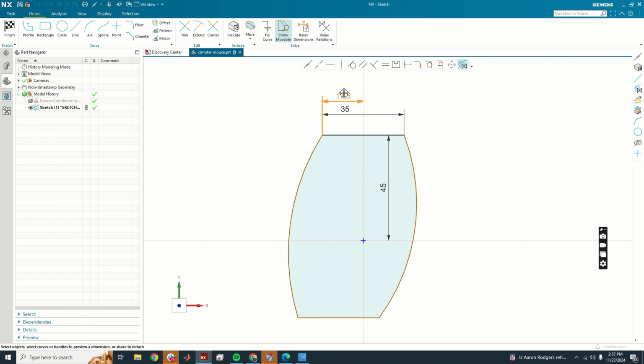That's what I want. Also, by the way, if you ever wanted to delete a relation, I will show you how to do that now. Basically, you just hover over the line, and then it's showing this little circle around that dot. That is a constraint, a coincident constraint. So I basically have to hover over that until it turns red, and then I left click, and it turns pink. And now that is sort of relaxed, and I could grab lines and start moving them around.